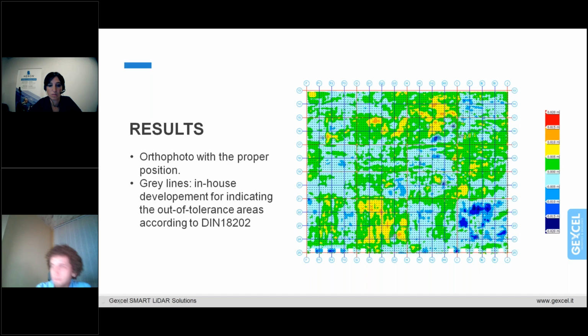And then the results. We have already the orthophoto, which can already be seen, the rectangles, however the concrete floor has been made during the different phases, you can identify the high points, the low points, and already according to this information, you can get a good idea where the bumps are going to be which cause the problem.